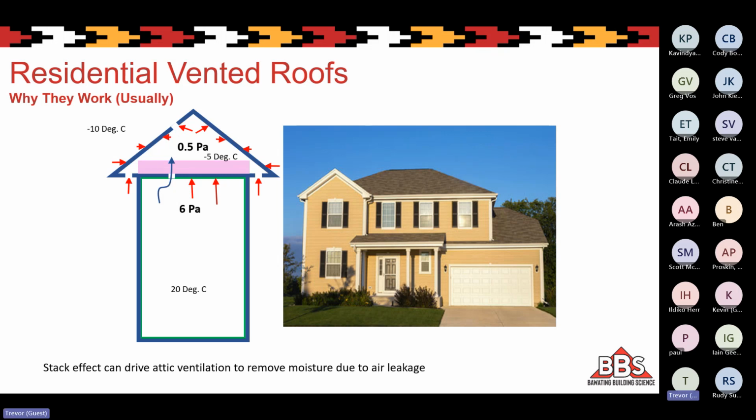And when it comes to ventilation, we also have the benefit of stack effect again, right? So it's not the same pressure levels we're seeing, but if we have, let's say, because of heat loss and air leakage into the attic, it's -5 in the attic when it's -10 degrees outside, that still gives us a 0.5 pascal pressure difference from in the attic to outside. And so when we purposely put ventilation holes near the peak and near the bottom, we get natural flow of air in at the bottom and out at the top due to this pressure difference that's been created due to stack. So stack effect, even though it's hurting us inside by pushing air into the attic, it can help us in our attic.